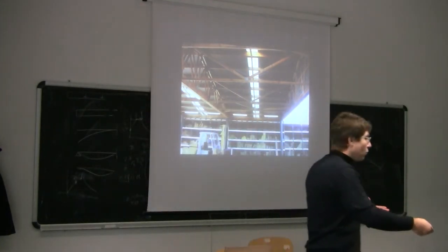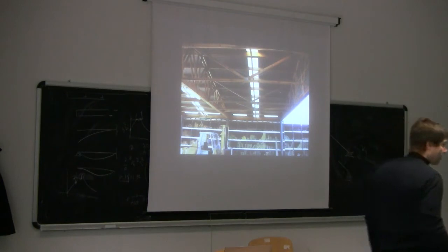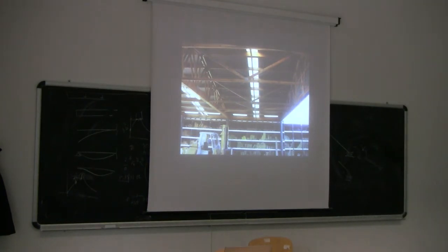Now, I would ask you, why is it not enough, for example, to put only one member here? Do we need to put the whole truss system? Your opinion. Would it be enough to put only the bottom chord, for example, rather than to have the bottom chord, the top chord, and the diagonal for this additional system, which is more than a bracing system, actually a system aimed to prevent lateral torsional buckling?